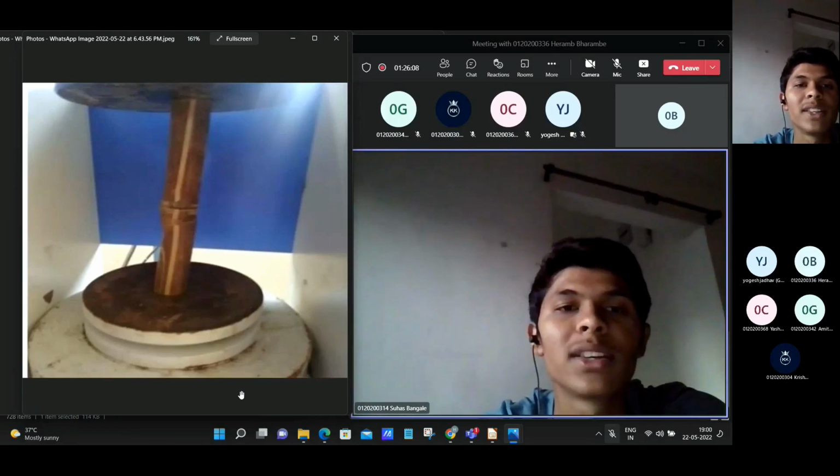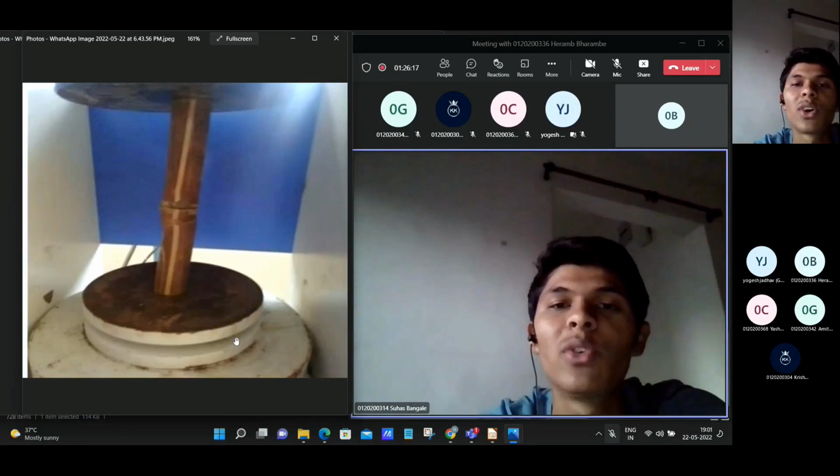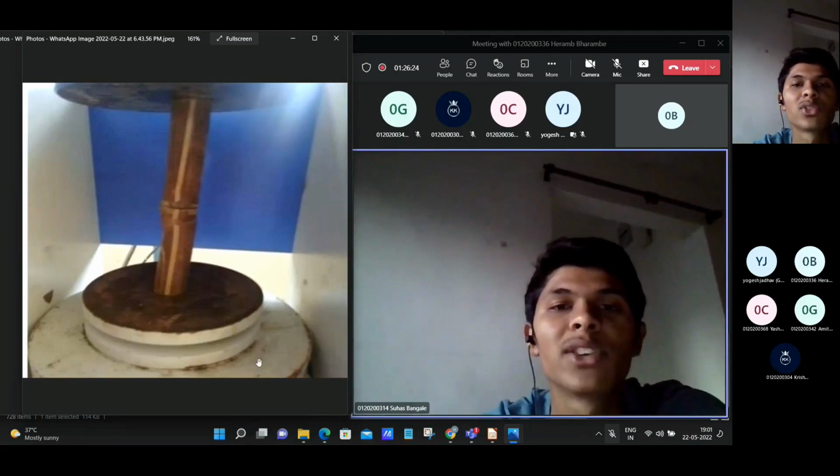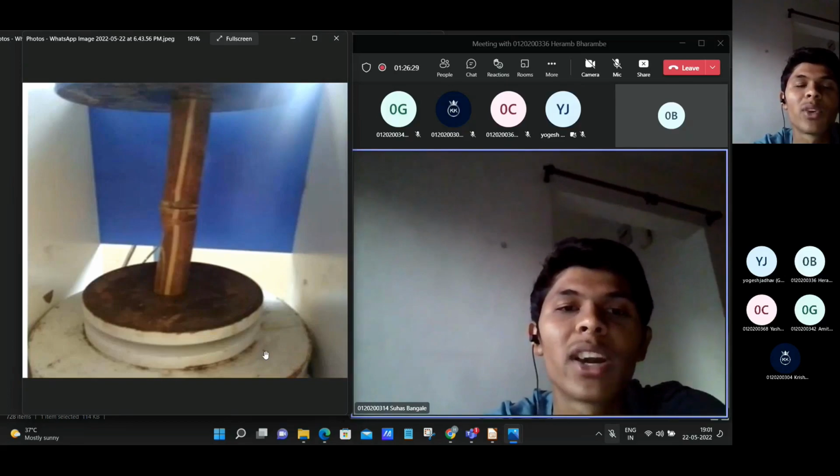The fascinating properties and uses attracted engineering researchers quite late, and various researchers started working on bamboo for its use as a structural material. The laboratory tests are carried out as per ISO specifications. ISO recommends that specimens shall be taken from the bottom part, the middle part and the top part of each culm, and these specimens shall be marked with the letters B, M, and T respectively.